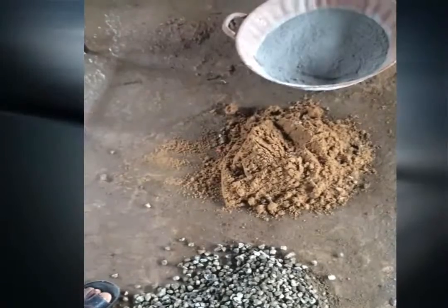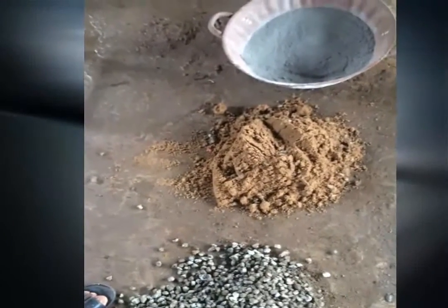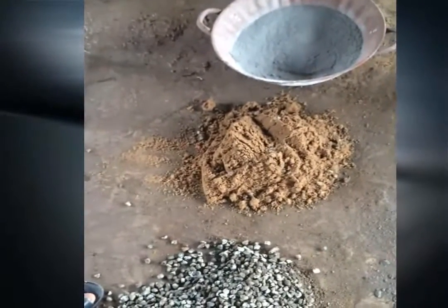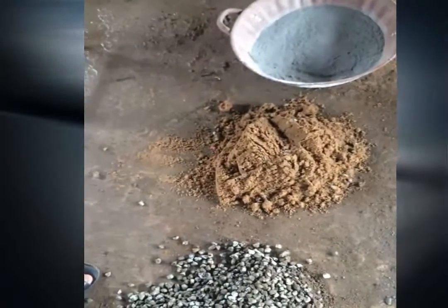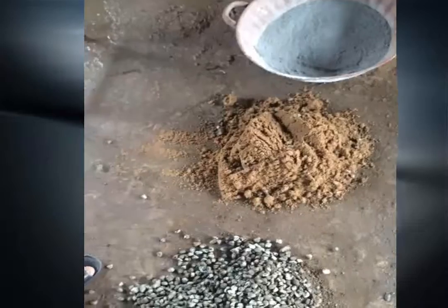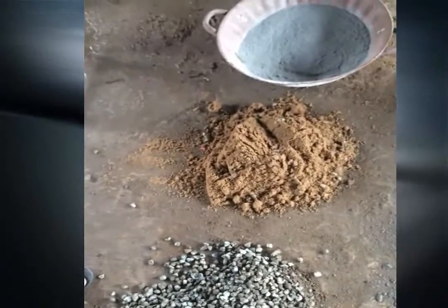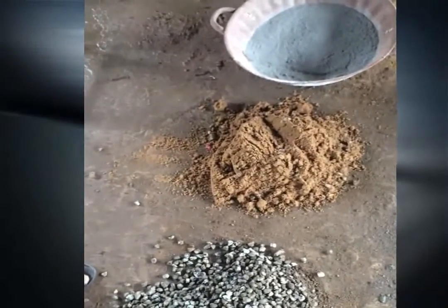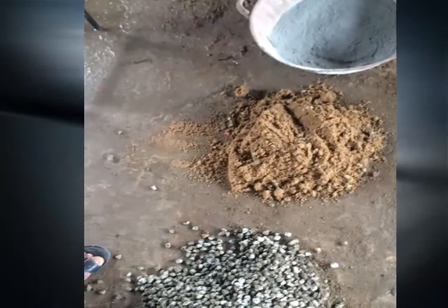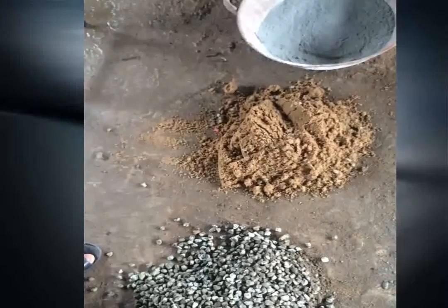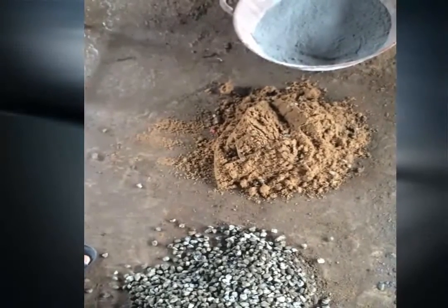When using a 150 millimeter mold, the concrete sample is scooped into the mold in 3 equal layers of 50 millimeter each and compacted between each layer. Hand compaction, that is manual, or mechanical compaction, that is a vibrating table, can be used to achieve the test.